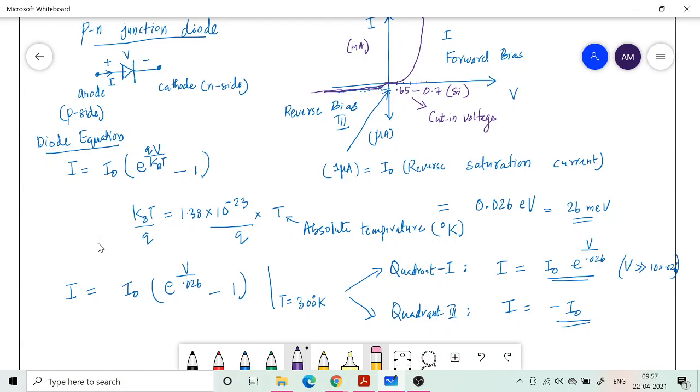The current enters into the milliampere regime, or at least a fraction of a milliampere, which is visible when you plot the forward bias characteristic. So here we go like 1, 2, 3 milliamperes, and here we go in fractions of a volt, 0.1, 0.2, 0.3 etc. Whereas when you plot the reverse bias characteristics, you usually go like -1, -2, -3, larger voltage, and here the current is in microamperes.